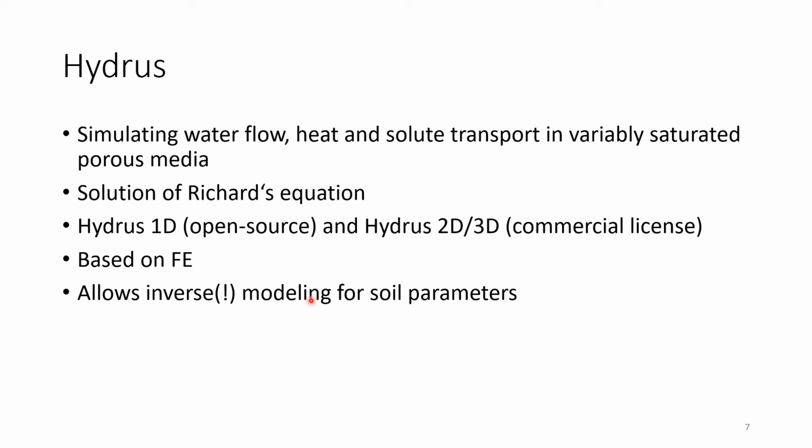And there's also a very nice feature which allows you the estimation of soil parameters if you've got experimental data. So for example, if you come with an infiltration experiment and you know how your moisture content changed over time based on some boundary conditions, Hydrus allows the inverse modeling of soil parameters, right? So if you don't know what inverse modeling was, go back to the very first lectures of this series and look up again what inverse modeling was. But this is a very nice feature. But again, Hydrus should be connected in your head with partially saturated porous media.